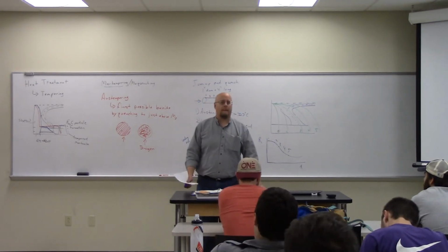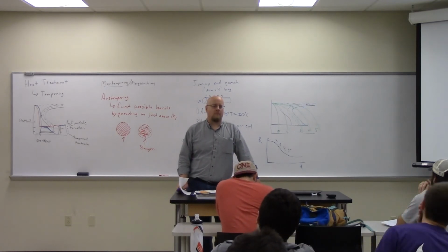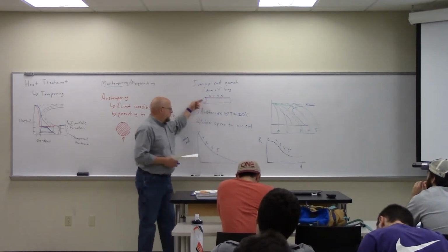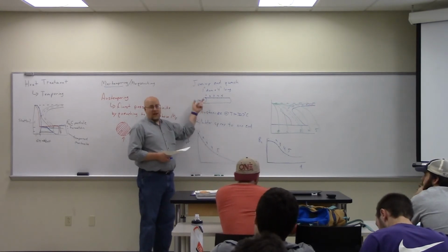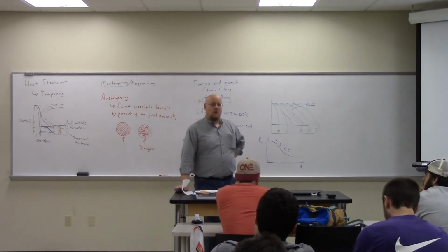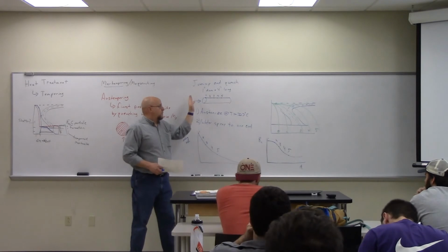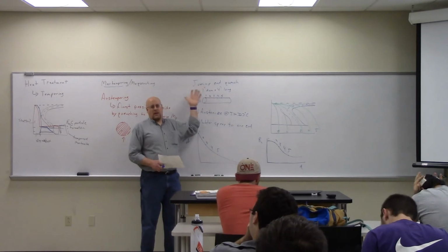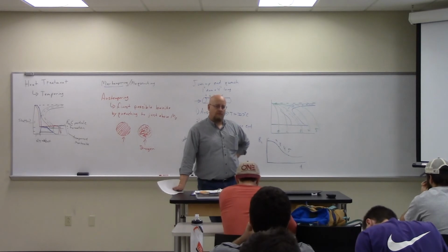Yes? What if you had a different cooling rate? On the plot in the book it says 700 degrees Celsius per second. Yeah. So what if you cooled it faster? Well, that's what I'm saying. That's what you get by squirting this thing with the water. You get a specific starting point and distribution. If you wanted a faster cooling rate, you'd have to use colder water or a larger volume of water. So this is just a very specific case. The maximum is a very specific case, and then depending on where you are along the depth, you'll get everything below that. The maximum cooling rate is determined by the nature of what you're spraying, how fast you're spraying, and all that. Okay.